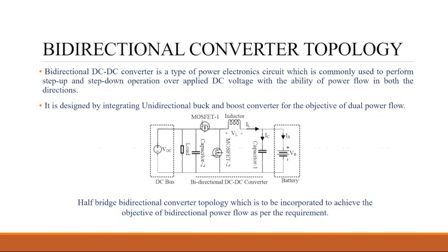So basically, what is this converter doing? This converter is combining both these two circuits. We are getting a buck and a boost converter, right? So this is how we are optimizing it. We don't need to use two different circuits. We can make use of both operations in the same single circuit. That is what is called bidirectional.